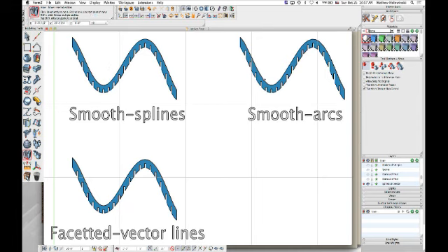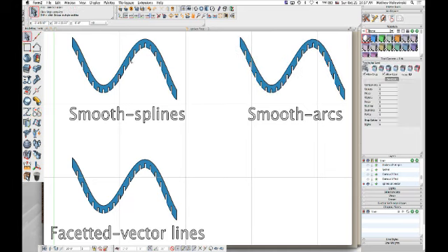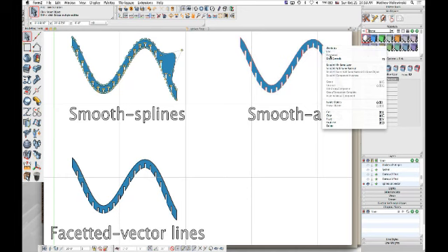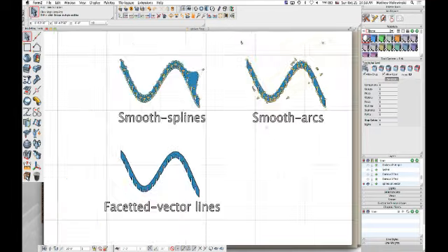If you need to convert that to a series of arcs, we have a convert to arcs tool. So all you have to do is use that tool on the object, and we can see the difference between these. If we have a spline, move one spline control, we have sort of a curve that interpolates through there. Whereas this one that's converted to arcs, you can see it's a whole bunch of arcs. So I go in here and show controls. There's the center points for the arcs, and there's one single arc there.